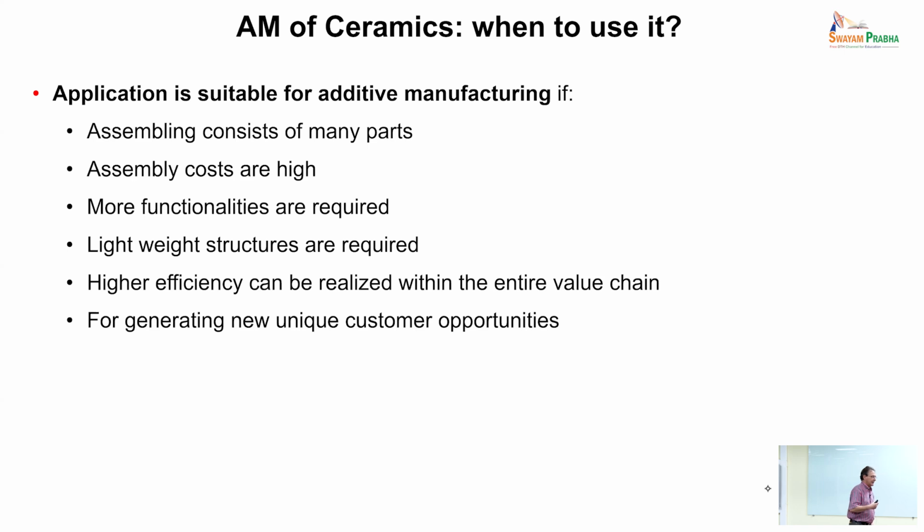And an architected material is a component where the properties are not given just by the intrinsic characteristics of the material, like melting point, refractoriness, hardness, mechanical strength, and so on. But the properties are given by the structure, the 3D structure. And this relates mainly to highly porous components. And so this new field of materials engineering uses structure as a way of guiding the properties of a component.